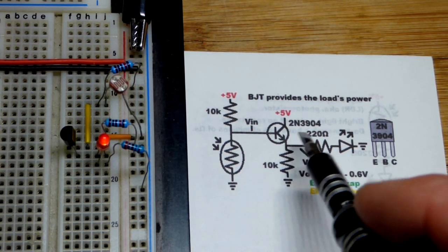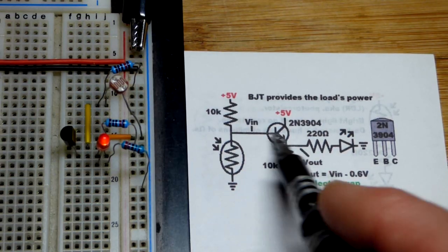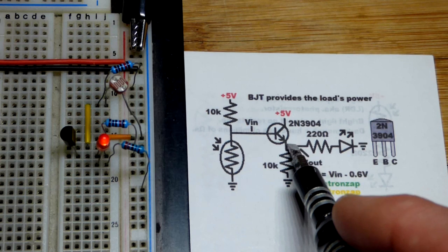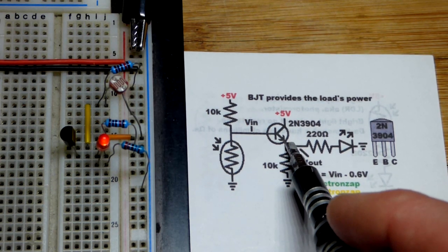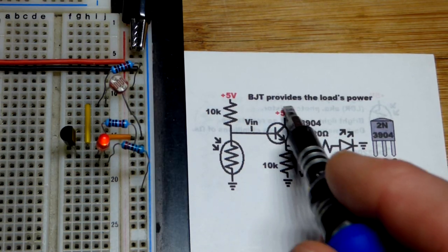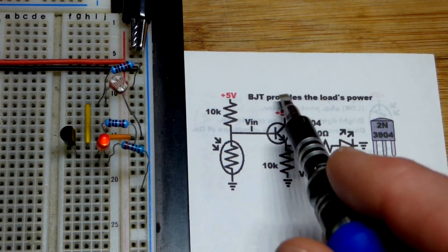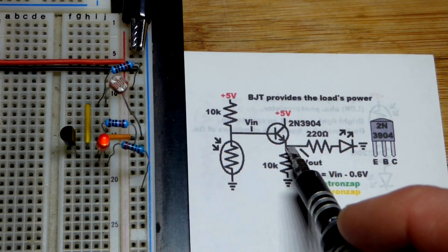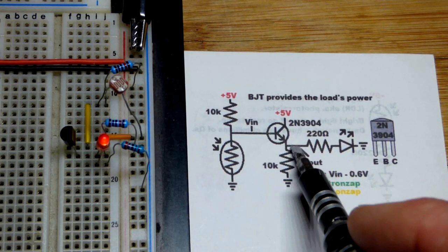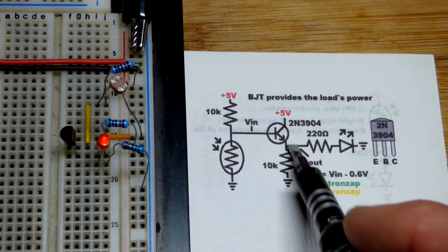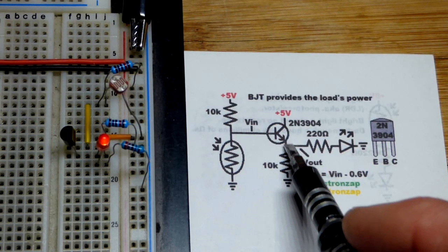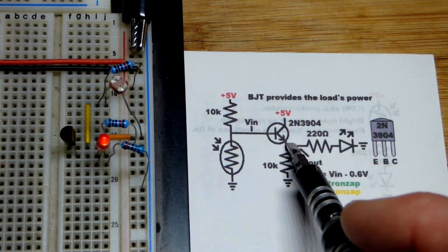Hopefully that makes sense. The base to emitter drops about 0.6 volts, so whatever voltage you set at the base, you'll get 0.6 volts less at the emitter. Once that voltage is established, the collector passes current as needed to maintain it. So you barely draw any current, much less than regular circuits where you're switching, because if more current flowed through, this would conduct better and raise the voltage even higher.